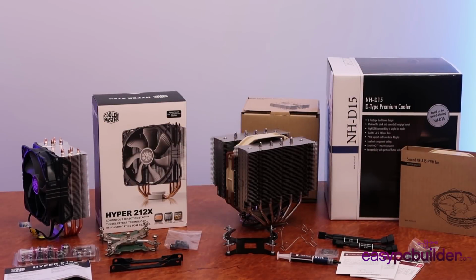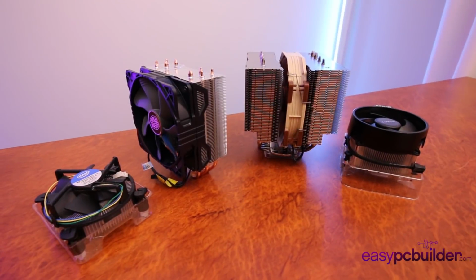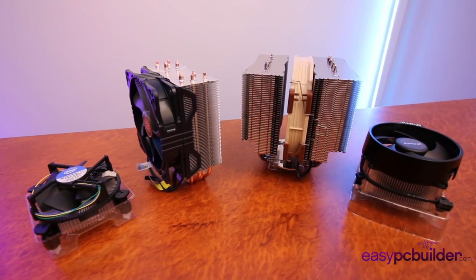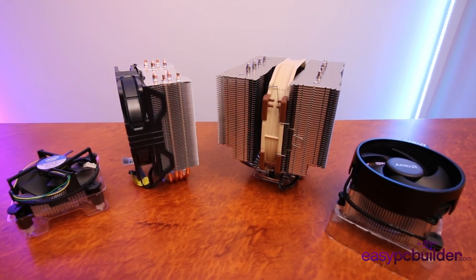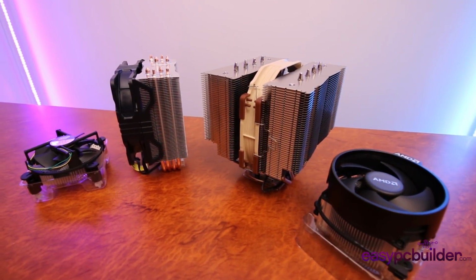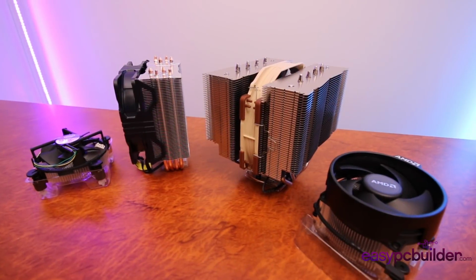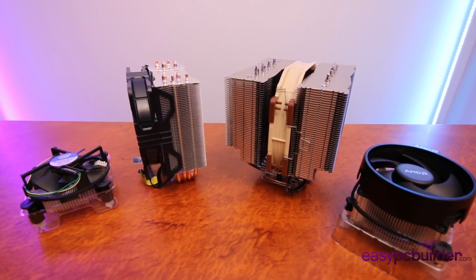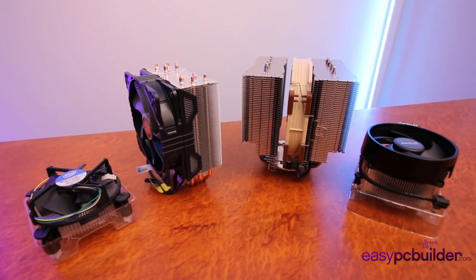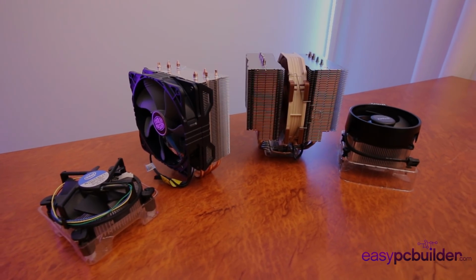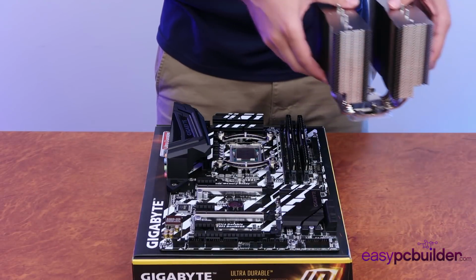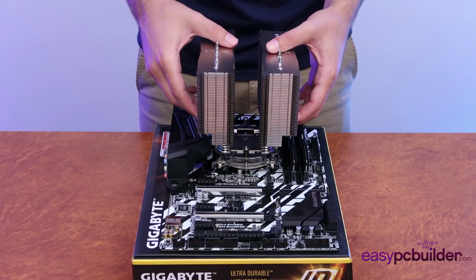So the efficiency of a cooler is dependent on the amount of surface area the heatsink has to dissipate heat. The larger the surface area, generally the larger the cooler, and if you have a larger surface area with a large or several fans, you can control the high temperatures much more efficiently. Another bonus is as the cooler is more efficient, at lower loads you don't require high fan speeds to keep the heatsink surfaces cool, resulting in a cooler and quieter computer overall.